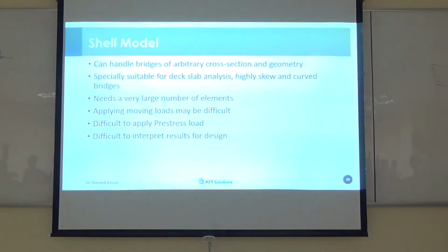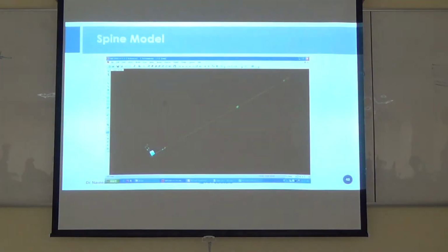Shell models can handle complicated bridges, curved bridges, skew bridges, variable depth, all those problems that you cannot handle in other models. I personally prefer the shell models a lot over all the other models these days because they're really good. You can just do a very good, realistic model for anything.